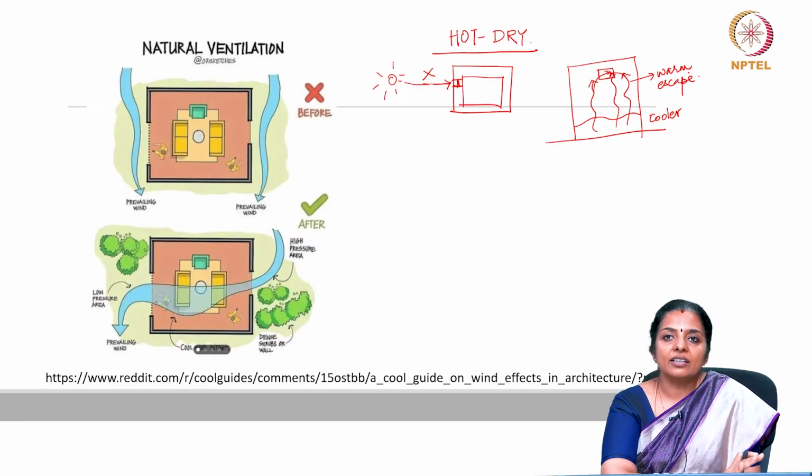Window location makes a difference to the quality of light obtained indoors. High windows, something like ventilators, provide the best distribution of the direct and diffuse light. However, they also maximize the potential for glare and should have baffles. Low windows allow ground reflected light. Light being reflected from the ceiling provides the most uniform illumination. The middle located window, in comparison, distributes neither skylight nor ground reflected light well.